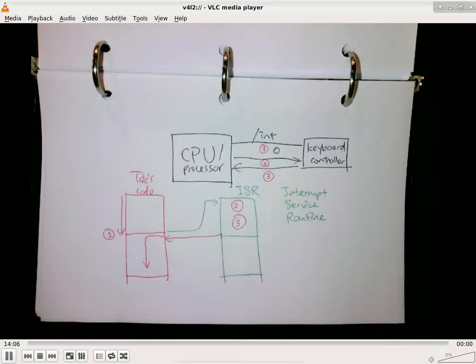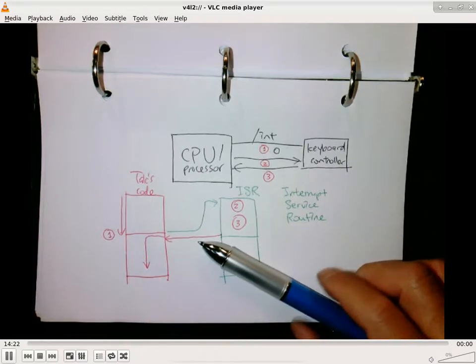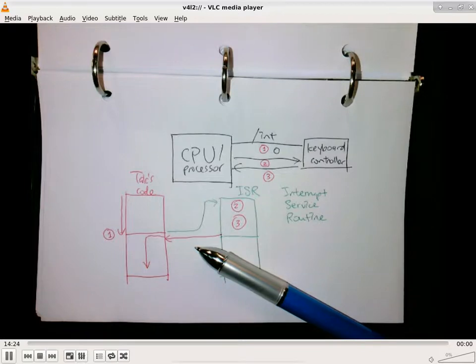What do you think the answer is? And why it relates to the question that you guys asked a little bit earlier of, hey, how come stuff that is below the stack pointer may get corrupted? So our issue is with this red line here. The line that goes from the end of the ISR, the interrupt service routine, getting back to the resuming point of my code. How does it know where to go back to?